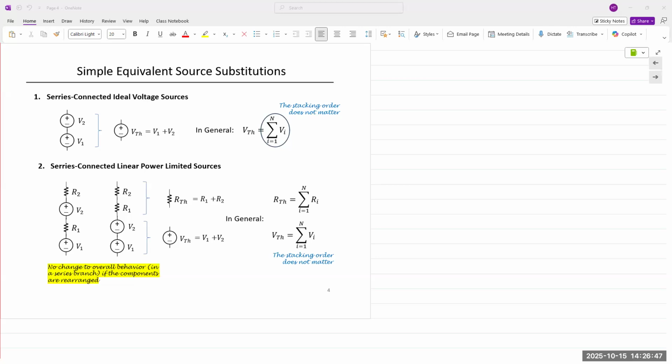The voltage measured at those terminals is the Thevenin voltage. The current flowing between those two points is the Norton current. And the resistance measured between those two points is your Thevenin resistance. In a lab, if I were to do this procedure, it would take me less than 2 minutes. It would take you less than 2 minutes.